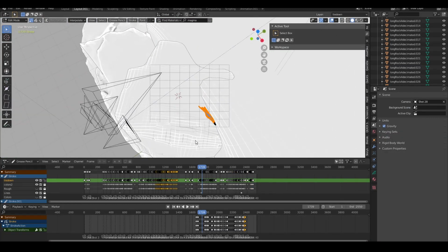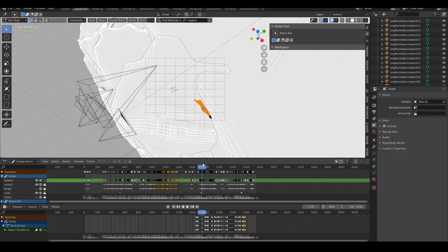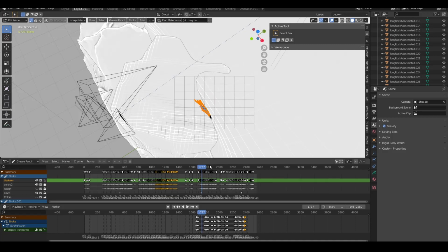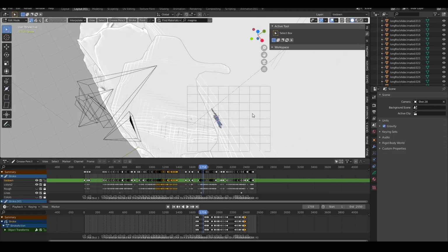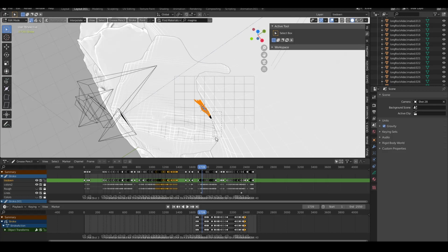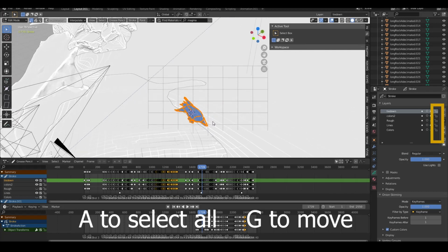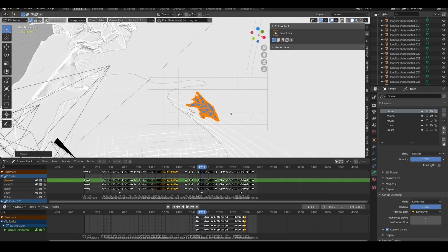Say I wanted to change, so I'm looking at this now, right? I'm flipping through with my cursor thing, and I'm like, oh, I kind of want him to move more through 3D space than that by this point. Then I would highlight the vertices and use my usual method of moving things. The reason that's not grabbing that is because the other layer is locked. So if I want to move all these down, I press A, and then I can move the character in edit mode, and that's how you do that, right? So it's not done in object mode.